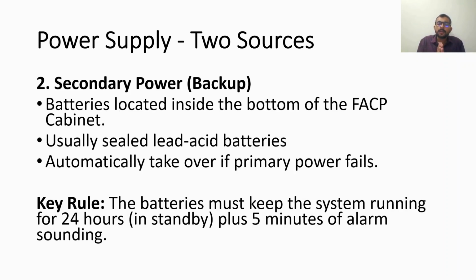One of the key rules that we engineers need to follow while designing the battery is that the batteries must keep the system running for 24 hours in standby, plus it has to run for at least 5 minutes to notify for the alarm sounding.